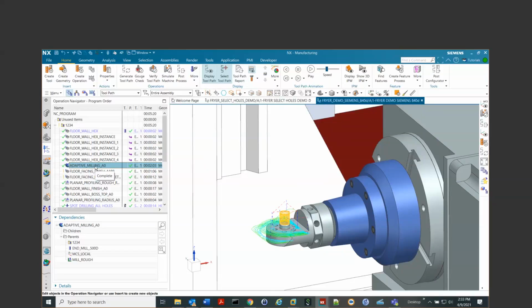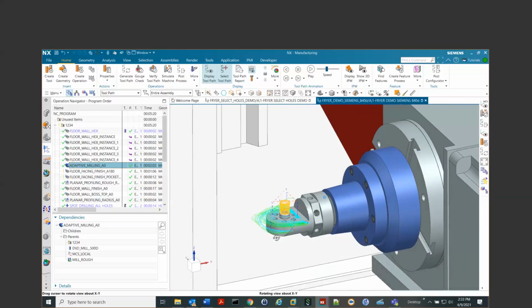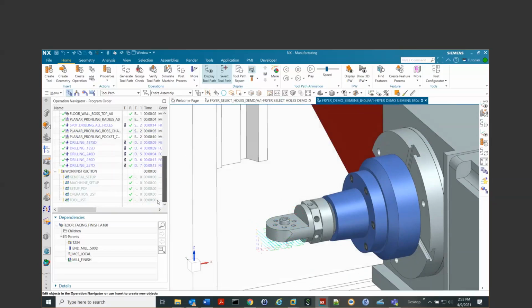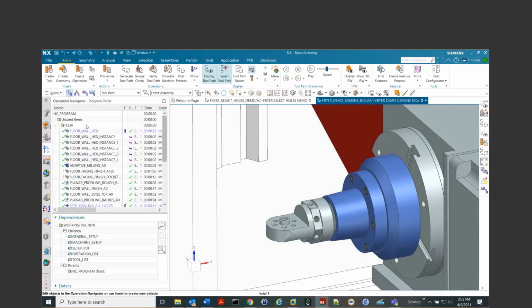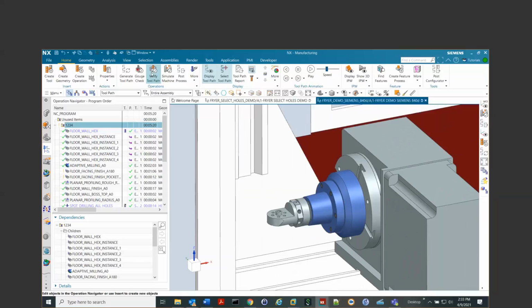Actually, everything is being done with a radius type of cut, so there's no right and left hand turns. And the rest of the part was programmed like we showed earlier. And here's the work instructions that I've created inside of NX that I showed you just before. I come up here and I go ahead and say, let's go ahead and simulate the machine now.